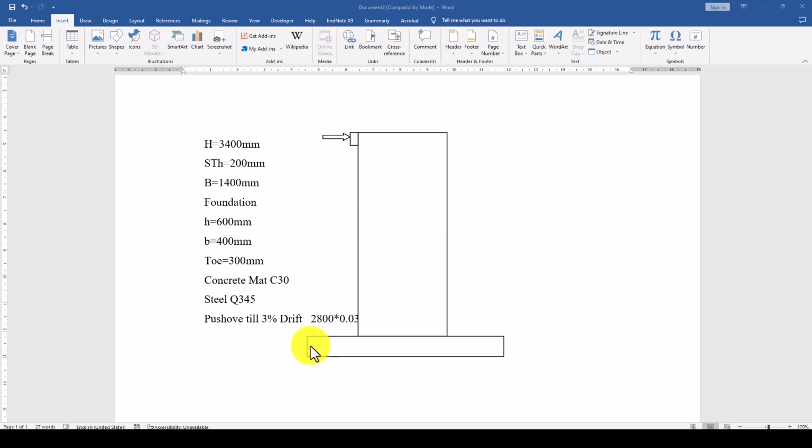But we're not considering the rebar in the foundation because, as we know, the stiffness of the foundation is quite high, so damage will not be considered there, but instead it will be here. We make it quite simple. This is not a verification work, just a random example to show you how to use plane stress and how to assemble rebars with the 2D plane stress modeling technique.